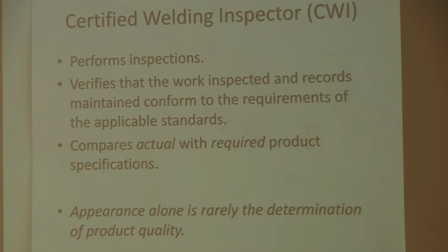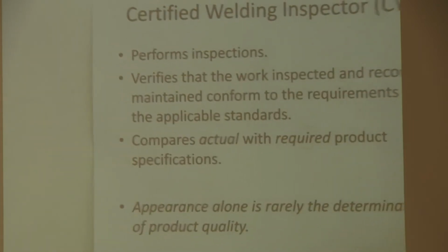When things are all done, he'll get out his weld gauges, he'll get out his magnifying glass or his flashlight, and he'll look things over and make sure that what's actually there is consistent with what was required in the specifications. And the big thing there is appearance alone is rarely the determination of product quality. So it's more than just looking. It's having an understanding of the whole process, having an understanding of what went into making that welded product, and being there as that process goes along.